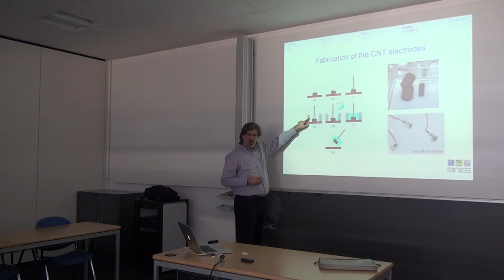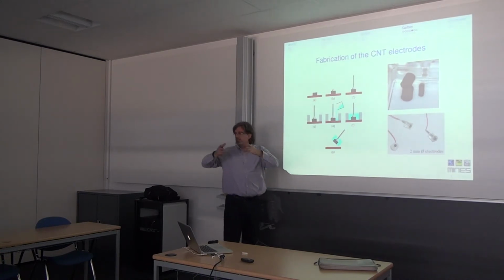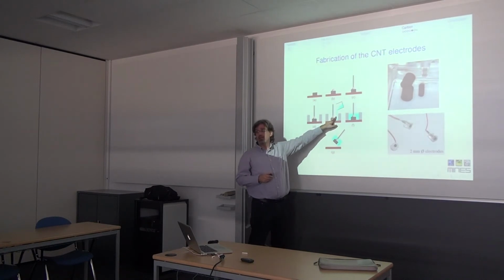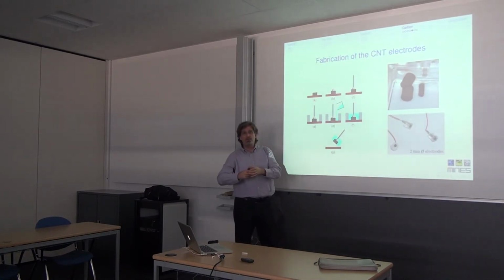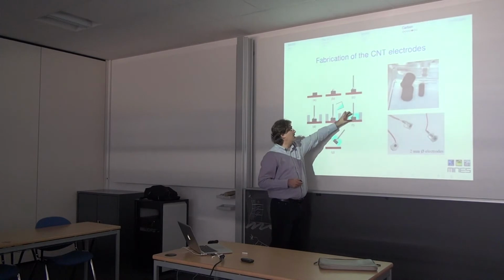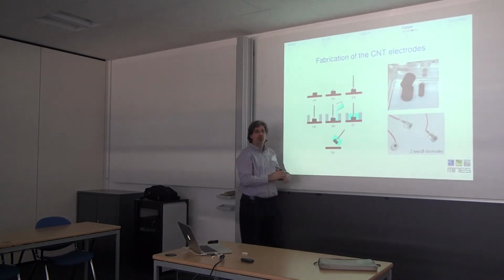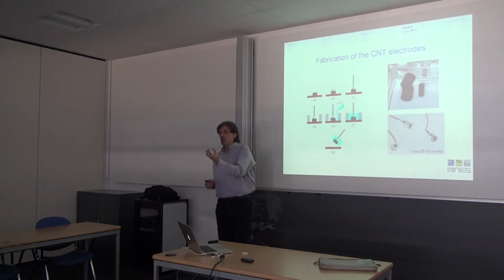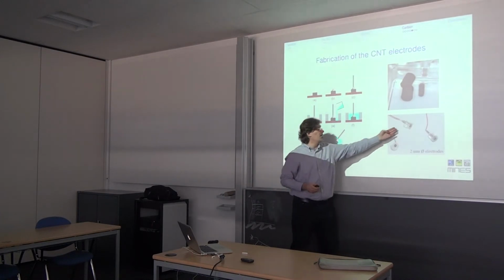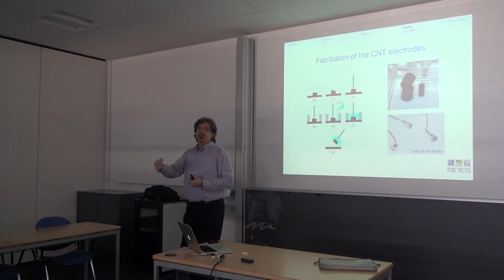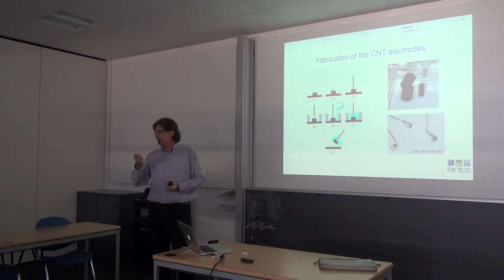We use PMMA here as a mask, and after we put the PDMS in the wells of the PMMA. We wait until everything becomes more solid, and after we can detach this structure that we produce, giving the connection but also a mechanical structure to the electrode that we can use.